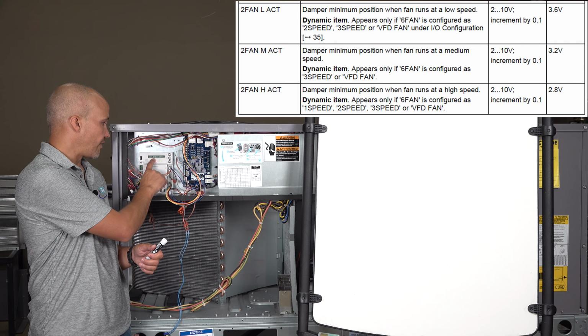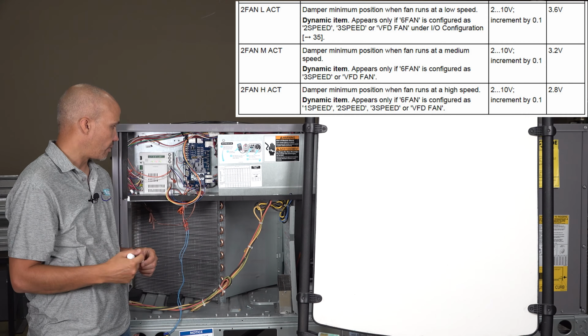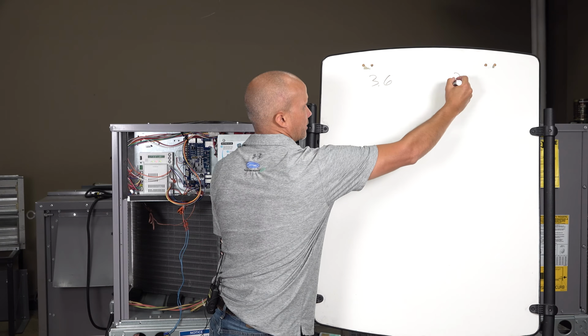So right now I'm showing you fan low actuator position 3.6 volts, right? And then the high one is 2.8 volts. So let's keep that in mind, and we'll go through this here.